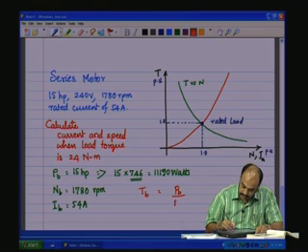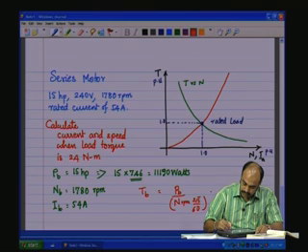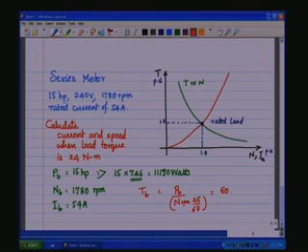But we have the speed in RPM, so n RPM into 2 pi by 60 would give radians. So it is 60 into 11,190 watts divided by 2 pi into 1780 RPM, which is 60 Newton meter. This is the base torque, TB.